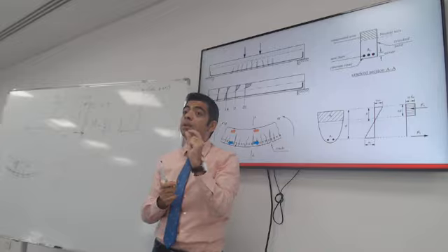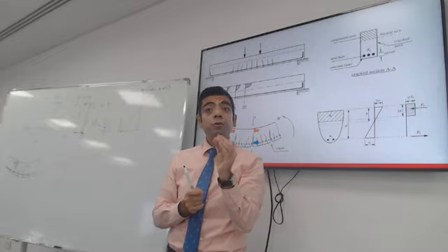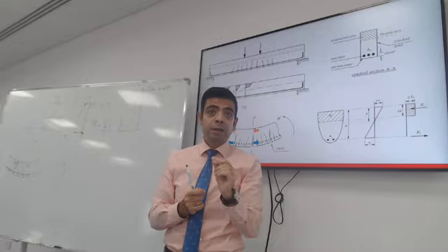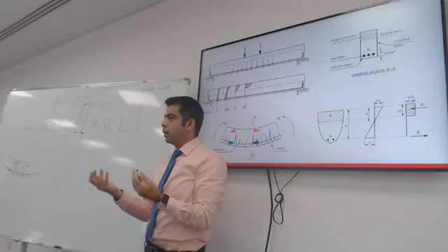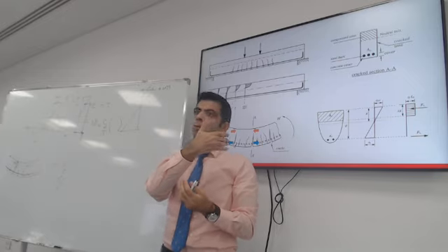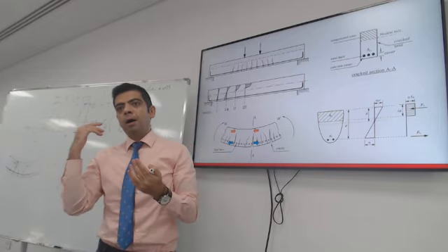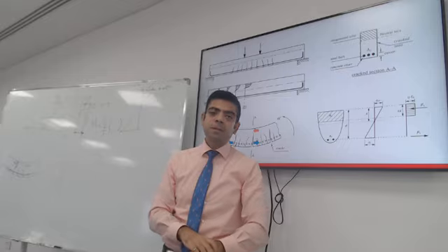Having said that, these cracks are very small, to the point that you need to control the crack width, especially if your structure is going to be exposed to moisture or water. You don't want water to work its way through these cracks and cause damage to the reinforcement, which will very quickly reduce the capacity of the section.